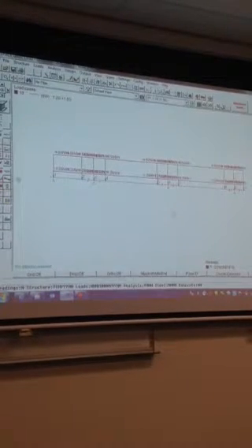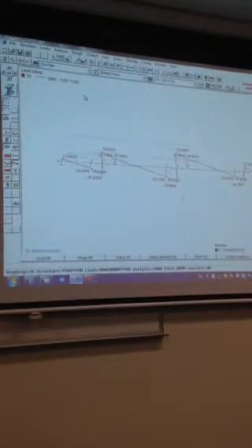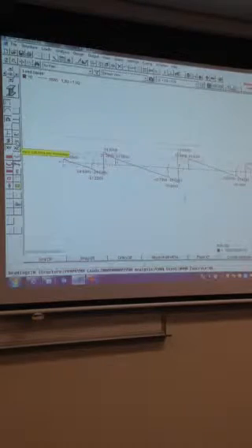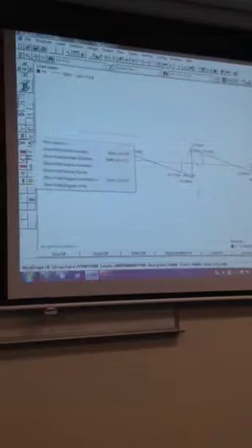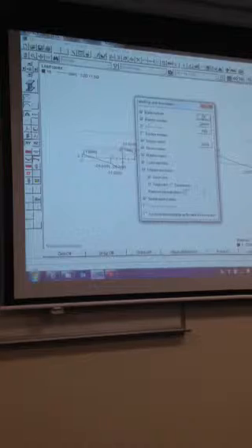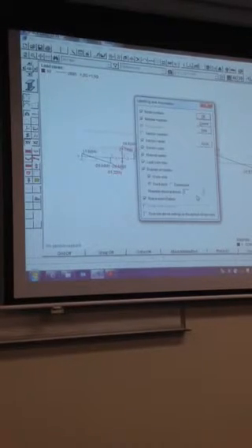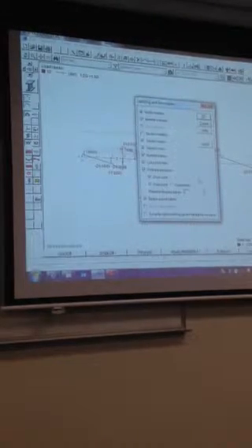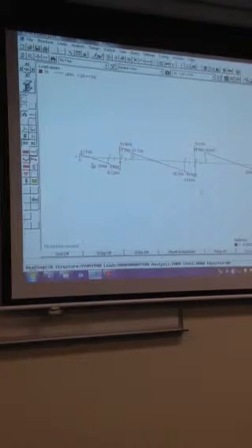Now if I come down to load case 10, I'm going to turn those loads off. So it actually generates for us bending moment diagrams and a shear force diagram. Okay? It's going down to 2 decimal places. I don't really want to see that. So you can change that around. You can go to where it's got the number 2, and you can turn off nodes and other bits and pieces. But what I'm going to go to is more options. And I'm just going to say I want 1 decimal place. It makes the numbers a bit easier to read, and it rounds them up.